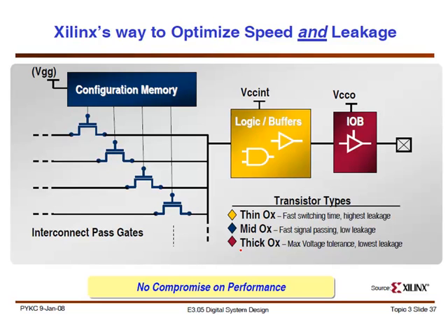basically looking at the functionality of different components in your FPGA. So you have your configuration memory that needs to be low leakage, right? The configuration doesn't change its values. Once you program your FPGA to do FIR filtering, you don't want to go back and change that to IIR filtering every cycle, right? I mean, you would change configurations very infrequently. So those need to be not necessarily very fast, but you want them low leakage, right?